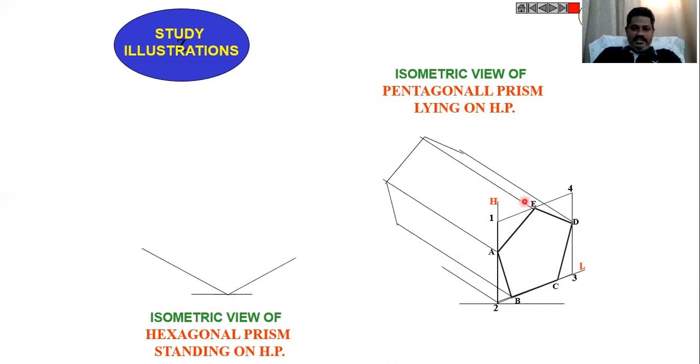It looks like this. Construct a pentagon in front view, then draw the lines which are at an angle of 30 degrees, parallel to this line. Then join all those end points to give the pentagonal prism with one of the faces lying on the horizontal plane.